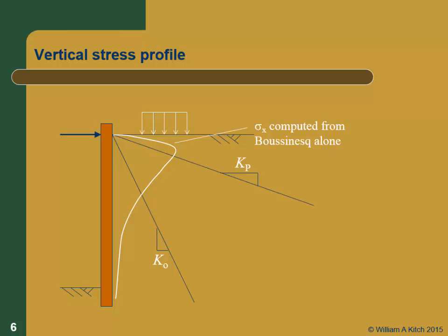Well, some of that can't exist, right? Obviously, I can't have anything that is above the KP, and because of the dynamic loading, it's not going to be less than K0. And I can go through a little exercise, and Peck and Mesri do this for you to show what the theoretical distribution of stress is. This is kind of assuming you have infinitely thin layers, and you just keep building it up and up and up.